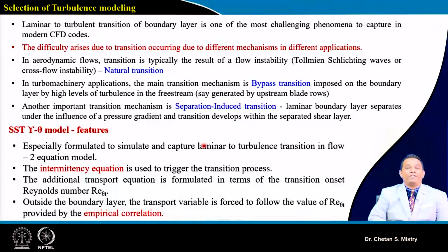Now when we are doing our analysis, suppose a cascade tunnel, it may have a low turbulence effect. This turbulence effect is what will bring a change in the transition on the surface. So mainly in the initial stage of analysis, we assume this turbulence intensity to be 5%. In an actual engine also, turbulence intensity will range maybe from 5 to 10%. What kind of flow is flowing inside my engine is what basically gives us an idea of the turbulence intensity.